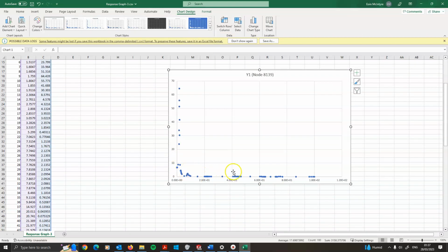And you'll see here the way it clusters the simulation tests that it runs. It clusters them around the first natural frequency, second, third, fourth, fifth, etc. Okay, so you see there are occasional simulations that are run in between those frequencies, but really it concentrates the simulation studies that it runs around the natural frequencies. And you can set that up in the simulation properties.